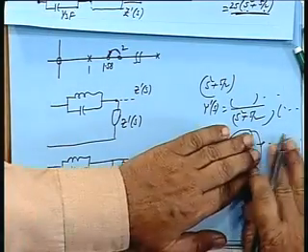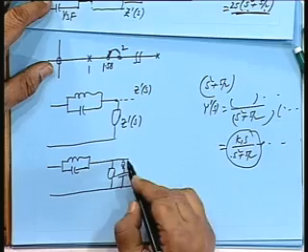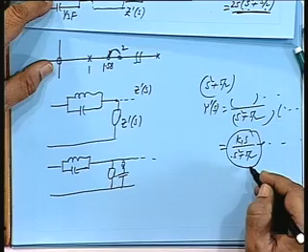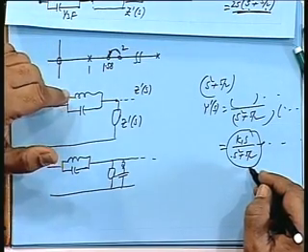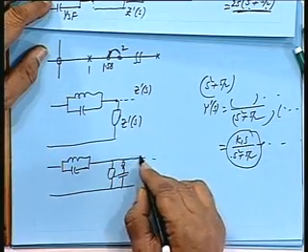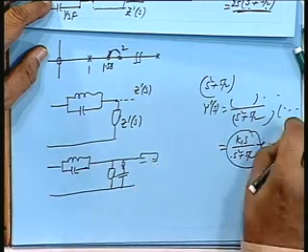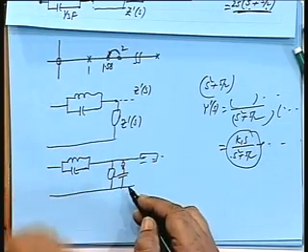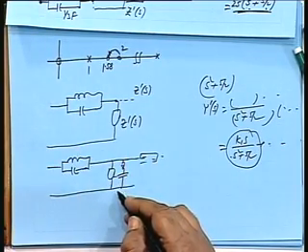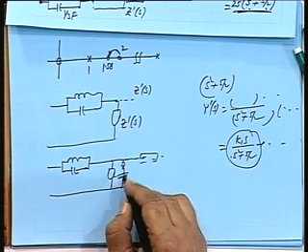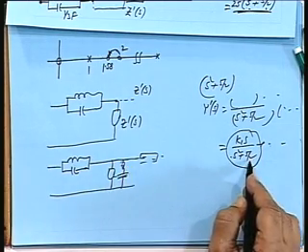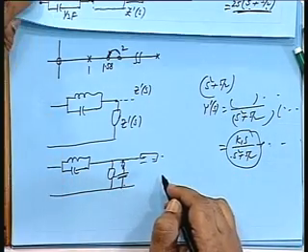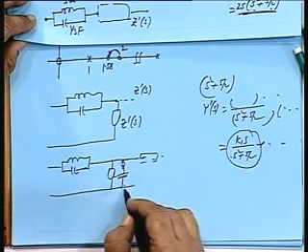And then the rest of it I will again switch over to ZS. I am not bothered about this part, I am interested only in removing that 0. So, convert it to a pole, that is go to an admittance function, realize that, and then again the balance you invert, you will get the rest of the elements. One by one you take out the zeros in the shunt elements. So, this will be resonating at root 5 by 2. So, that will be creating the 0. By partially removing the pole, we can realize this.